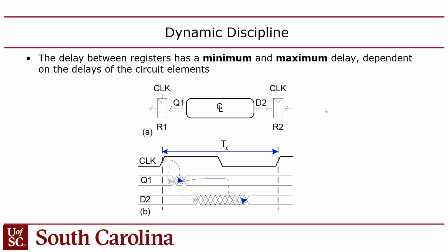Okay, so basically when you synthesize the sequential logic, and again, this applies to what I'm talking about here: if you design the stuff that we designed in the last lecture and then synthesize it, you end up with a design that looks like this, where you have a flip-flop, and the output of the flip-flop goes through combinational logic. The output of that combinational logic then goes into another flip-flop, right? So this is your data path, and this is how your CPU works, right?